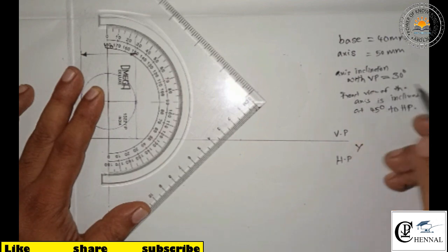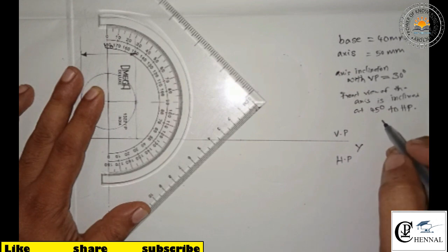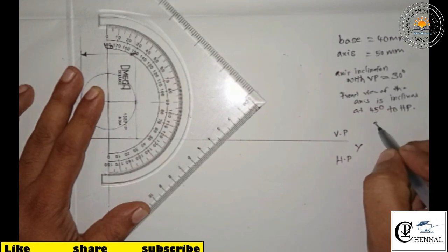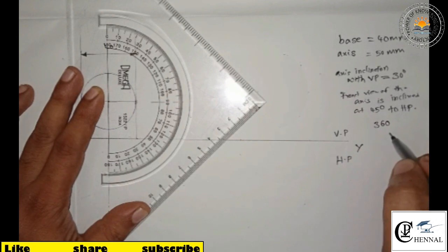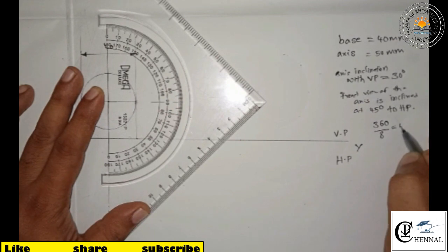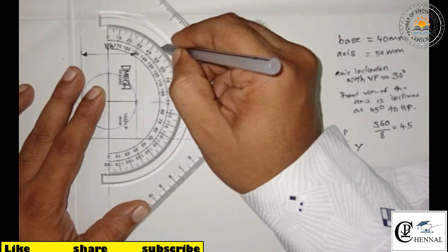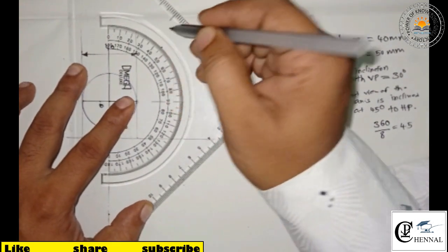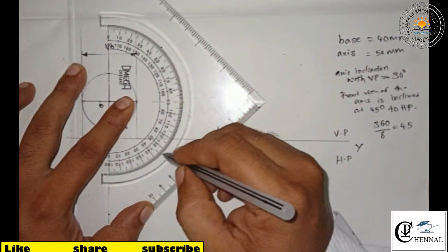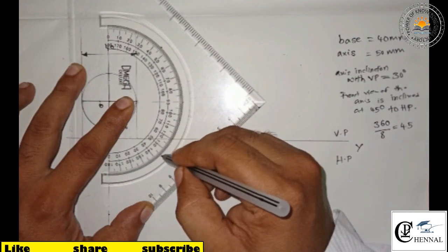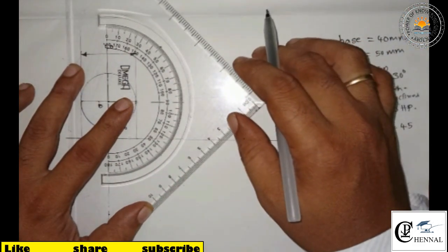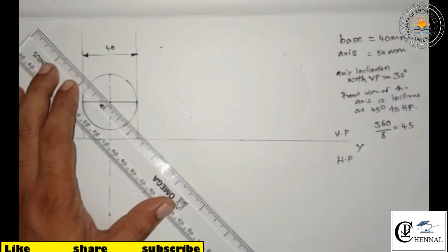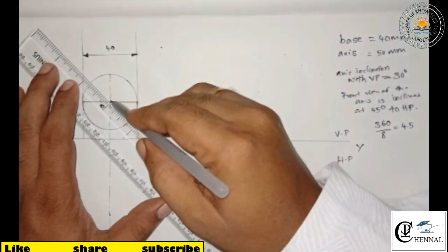Now divide the circle into 8 equal parts for obtaining a smooth curve. So that is 360 degrees divided by 8 equal parts, we get 45. So this is 45, 90, and this one is 45, 45, right? Now join the lines.